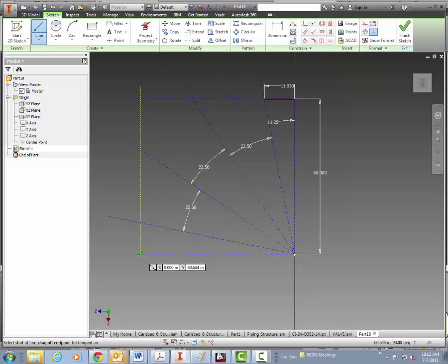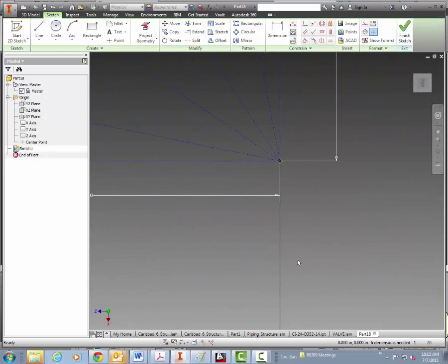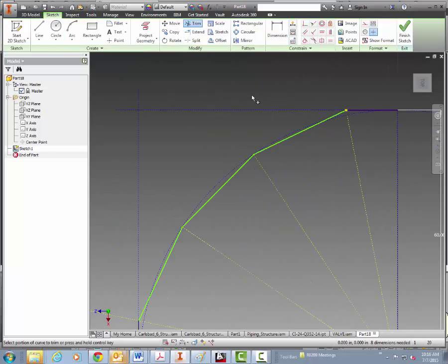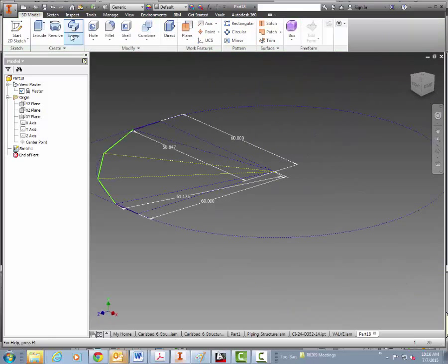And give it some dimensions for the center line of the pipeline. Now you can either enter these manually yourself and adjust the angles, or you can use a radius based on a circle that's also a construction line. Once that's created, we go ahead and put some more parameters to the lines to make sure that the dimensions have been finalized and the drawing is fully constrained.